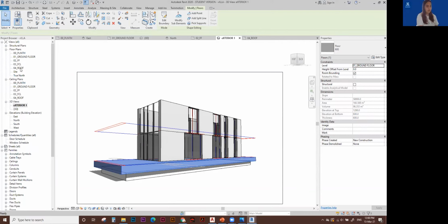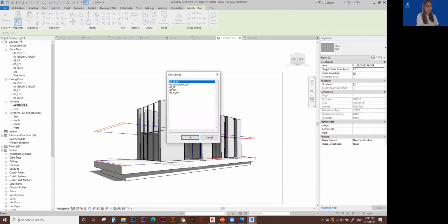And I want to paste it on, we know the level, right? We know the level is the roof level. So I want to paste it on the roof level. The way you tell Revit to do this is under paste, you have this drop down menu. So click on that. And you have several options here saying paste from clipboard, align to selected levels, align to the same place, and align to pick levels. So what I'm going to do is align to selected levels.